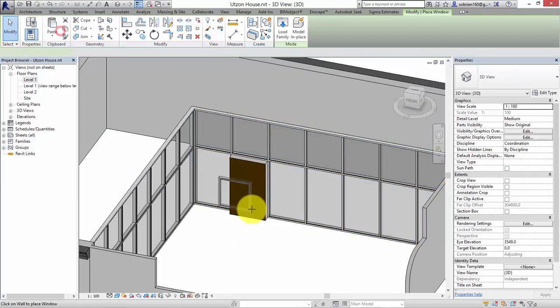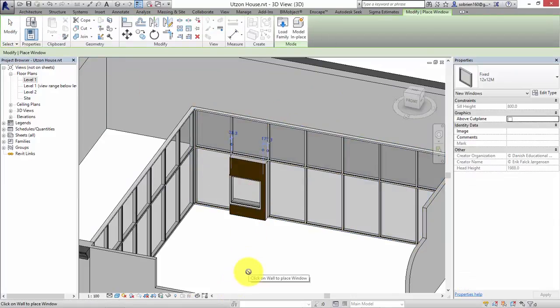And then if I want to, I could just stick a window in there, like that. So you can actually use it to make panelized buildings. If you ever look at modern buildings, they're often made with very prefabricated elements, large pieces of fiberboard or something that are placed together. So you can actually use the curtain wall to set up that kind of pattern and, you know, change it to whatever you want as you go along.